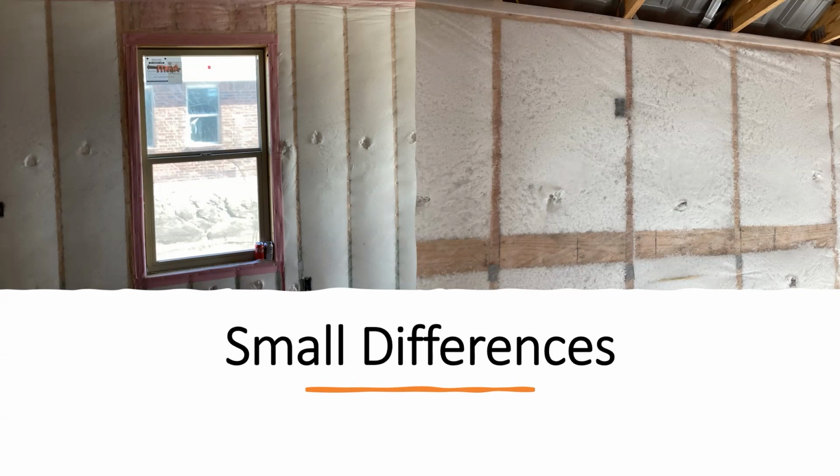If you don't feel resistance and it leaves an open pocket as big as your hand behind all of that netting, that probably should be listed as R13, or even question whether it actually has the right density installed to meet an R13. Because over time that insulation is going to compact. It's going to leave a gap at the top. It might look good now, but eventually it will start to collapse on itself just due to the weight, and it will actually make that difference.